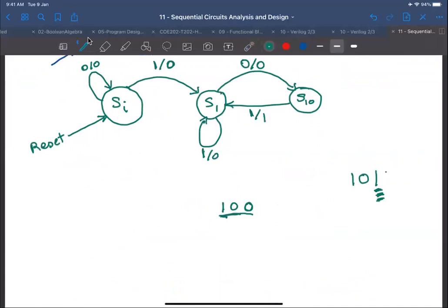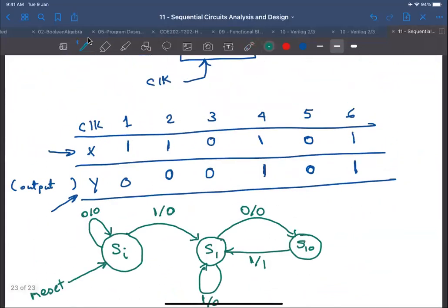Because here, if we are in 101, then we also expect a 01 to show up in order to detect the sequence again, like what we did in the example here. If you see 101, then we have a 1 here, and then 101, and then we have a 1 here. We used this one twice, for this sequence and for this sequence.